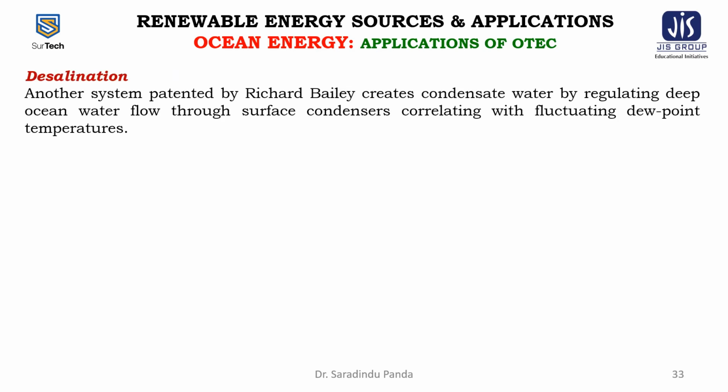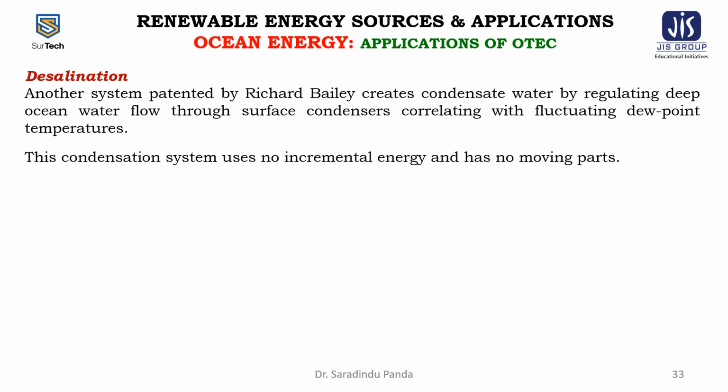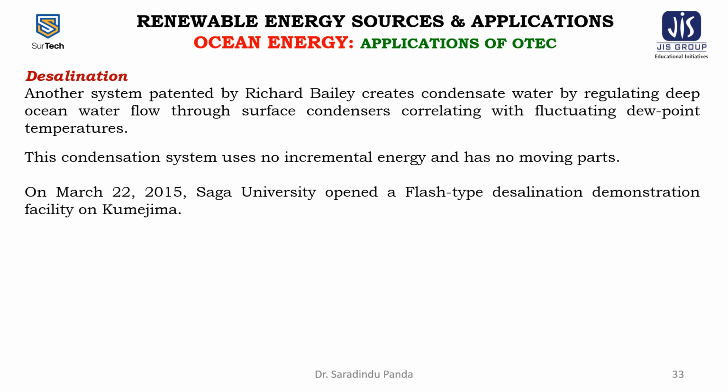Another system, patented by Richard Bailey, creates condensate water by regulating the deep ocean water flow through the surface condensers, correlating with the fluctuating dew point temperatures. This condensation system uses no incremental energy and has no moving parts.